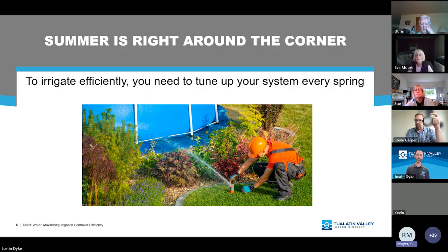Just watch if water's flowing where it shouldn't when everything's turned off. If everything is off, then you should see no movement on the meter dial, either the large red sweep hand, or the small little blue one, I call it the snowflake. That little blue snowflake, a low flow indicator, will spin even if a small amount of water is moving through the meter. So if everything else is off and you've only pressurized the irrigation system, you don't have any valves that are active, then that would be an indicator that you probably do have some sort of a leak in the main line.